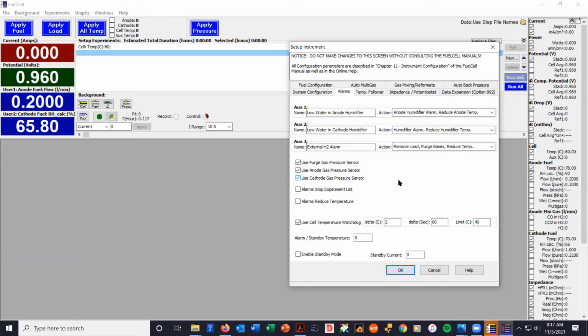But for people that have auto water fill systems, which is pretty much everybody nowadays, the requirement is that the test system have a source of pressurized water connected to it. And we describe what that pressure should be set at.